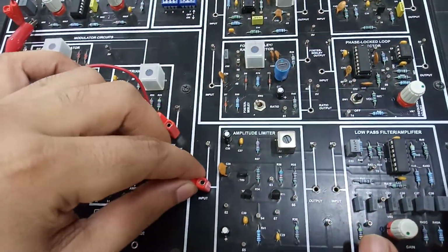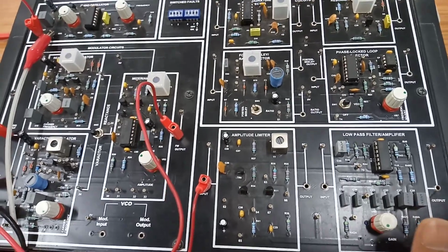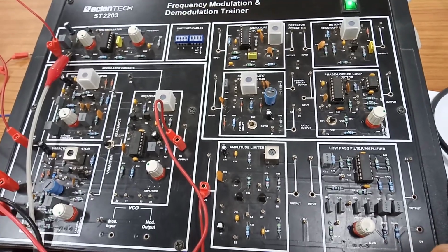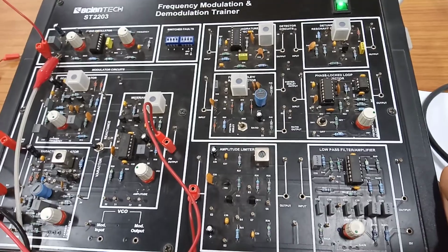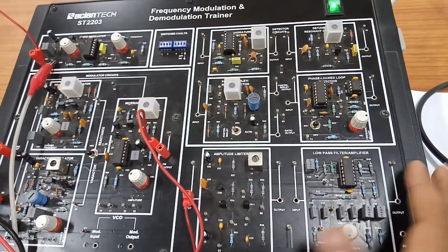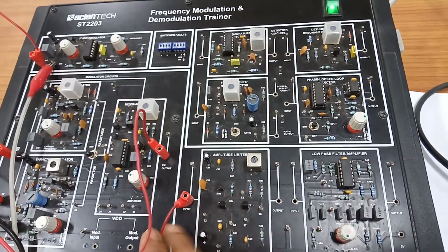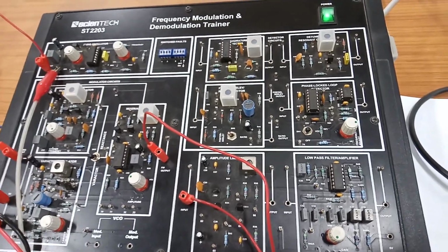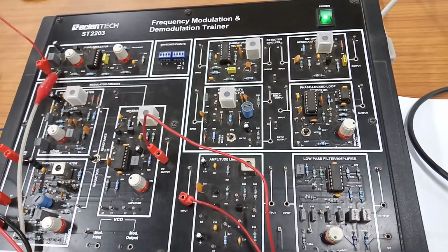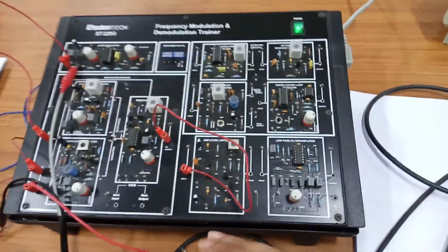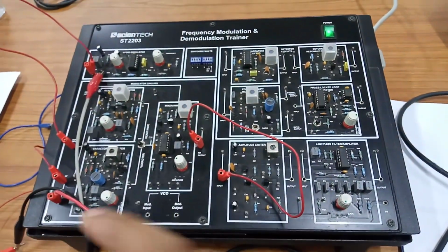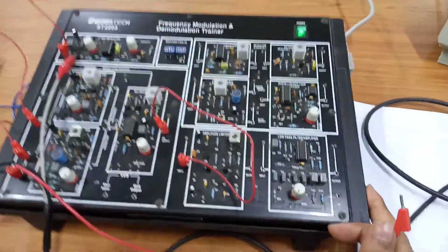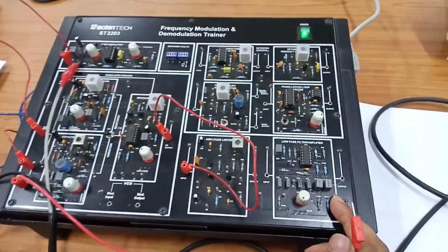We have connected this, and thereafter there are many methods for the frequency demodulation technique. The generally used ones are the quadrature type or slope detector type. In the quadrature type we get a 90-degree phase shift. You will come to know when I show you the demodulated wave. Here we are using the quadrature type, so we are going to get a 90-degree phase shift in the demodulated signal. When I say 90-degree phase shift, it means where there is a peak of amplitude in the input signal, we are going to get a negative peak or trough in the demodulated signal.